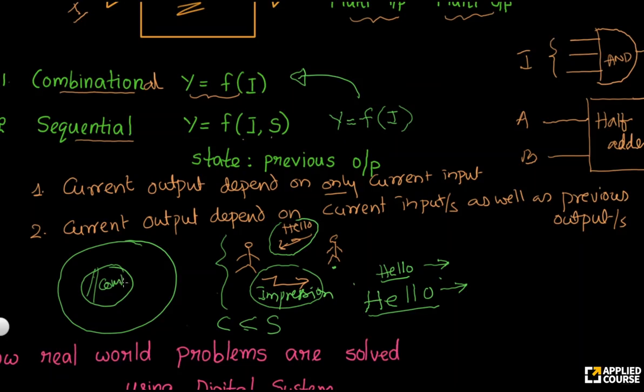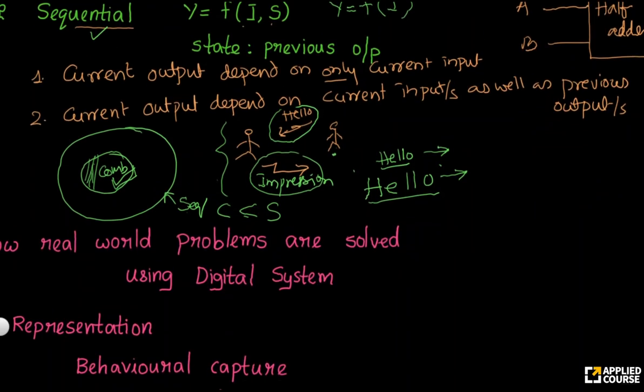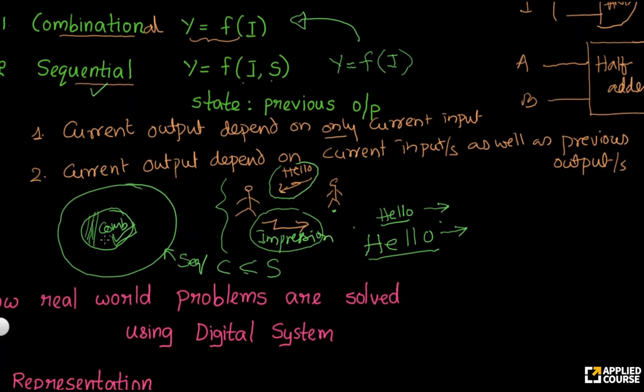So this is combinational, and this entire thing is going to be sequential. So what we do is we study initially about this combinational system, and after that what is contributing to the state, that is nothing but a memory element or a flip-flop, and we analyze the flip-flops later while discussing about sequential circuit. In other words, our entire preparation is focused on the combinational system initially, and once the combinational system is completely exposed, then we talk about the sequential system.